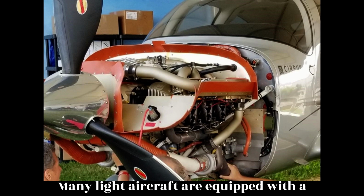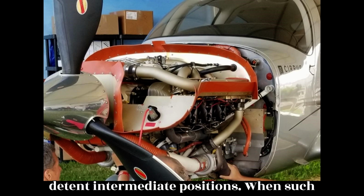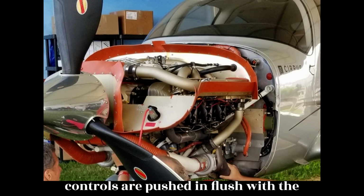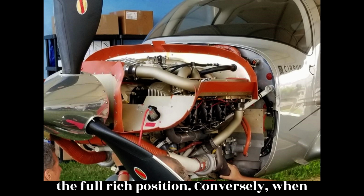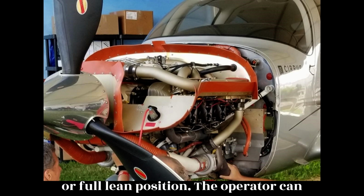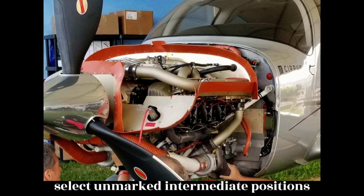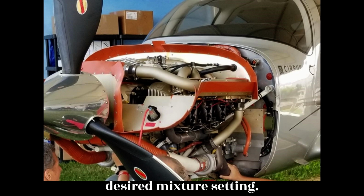Many light aircraft are equipped with a mixture control pull rod that has no detent intermediate positions. When such controls are pushed in flush with the instrument panel, the mixture is set in the full rich position. Conversely, when the control rod is pulled all the way out, the carburetor is in the idle cutoff or full lean position. The operator can select unmarked intermediate positions between these two extremes to achieve any desired mixture setting.